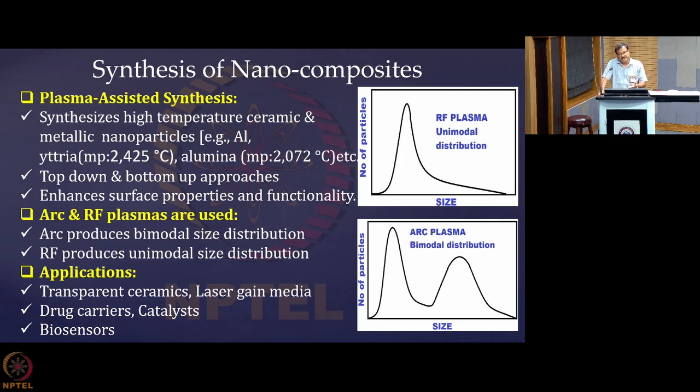Then you have to evaporate that to make atoms, then the atoms will undergo nucleation and form the nanoparticles. So the first step is the top down approach. You give some coarse material particles and evaporate them and form the atoms. Then when they have formed the atoms, you go for the bottom up approach. These atoms are now nucleating, colliding together and making bigger and bigger particles, and the coagulation stops at a certain temperature. Beyond that, they will collide like billiard balls. They will not join together.